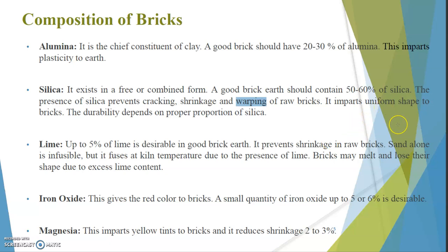So what are the roles of silica? It prevents cracking, shrinkage and warping of bricks. It imparts uniform shape to the bricks. That is the major role of silica in the clay which is used for making bricks.